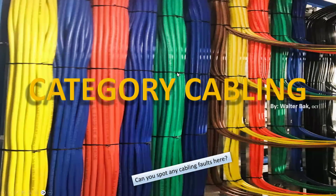And binding them like this, you also can create micro bends. Micro bends are destructive to the signal, because by deforming the cables, and maybe if somebody even steps on a cable, Cat 5e, if you step on it, walk over it, it will forgive you up to some point. Cat 6 and up will have no mercy on you. You step on that cable, you deform it, that thing changes its specifications, and it is better to just make sure that there are no problems with the signal. So the cable certifies as Cat 6.